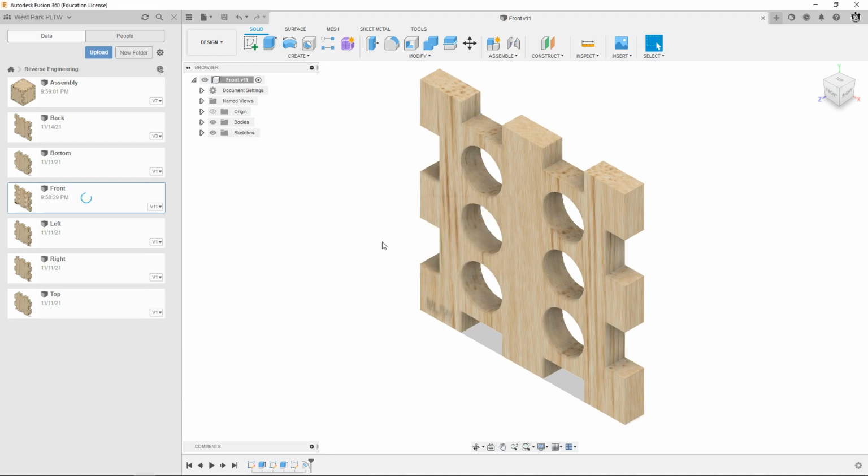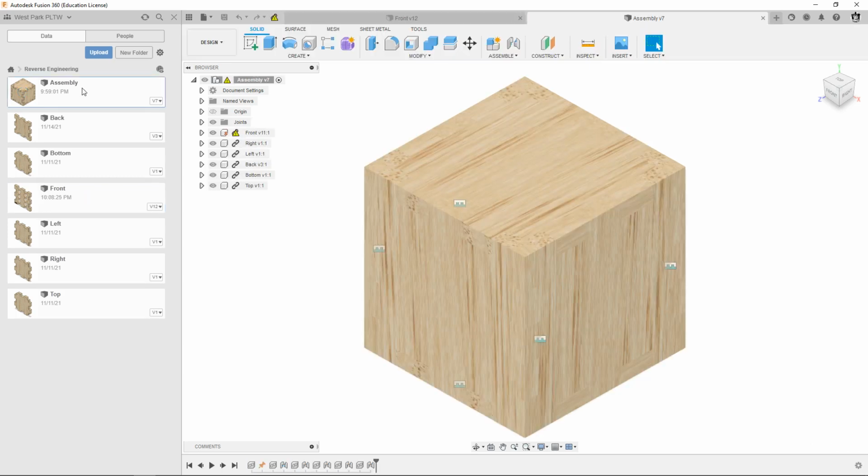And then we need to update our assembly. So I'm going to double click on the assembly to open it. There's my assembly. And you'll notice it doesn't have the 6 on it. And there was a little warning that flashed up. And you'll notice I have some exclamation points here. So what this means is we need to update the assembly. And the way you do this is right up here. There's a little thing, like an update thing, and it updates links. It looks like a chain because it's linked.